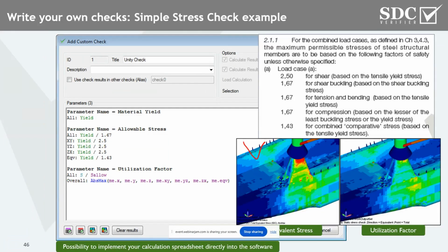the same FEM standard, you have different safety factors for different directions you would like to account for. And then when you compare your calculated stress to allowable stress, you end up with completely different situations. So people are interested to see, okay, this part is okay, this one is not okay. So for example, the red spots here do not mean that this is something that fails, because when you check it according to rules, it turns out that this is a tiny spot over there, and the rest of